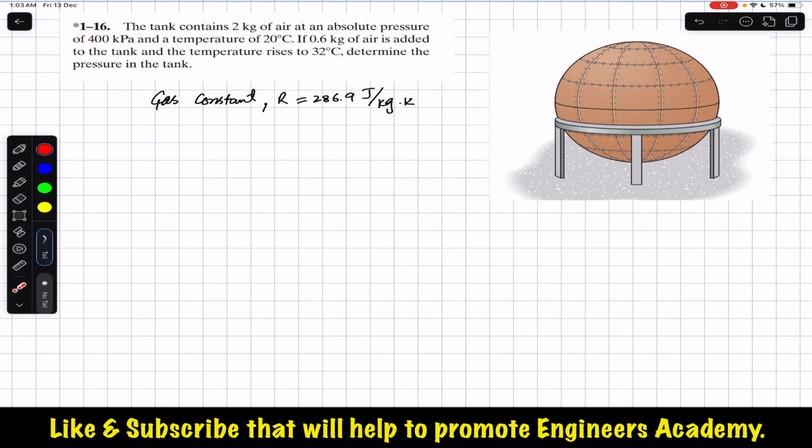Now let's solve this problem from chapter 1, Fluid Mechanics by R.C. Hibbeler. The problem says that the tank contains 2 kg of air at an absolute pressure of 400 kilopascal and a temperature of 20 degrees C. If 0.6 kg of air is added to the tank and the temperature rises to 32 degrees C, determine the pressure in the tank.